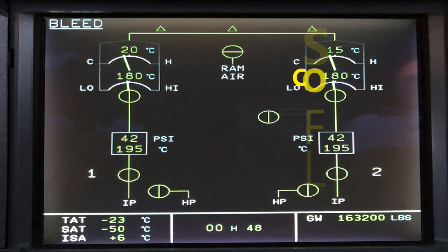And I'm not going to go into the basics of the valve. The valve just opens and closes. One motor opens it, one closes it. And it gives you a visual identification of the different parts of the valve, with the label, the valve body, obviously the flange, and your actuator motors. So it gives you an idea when we talk about the cross bleed valve and cross bleed system.